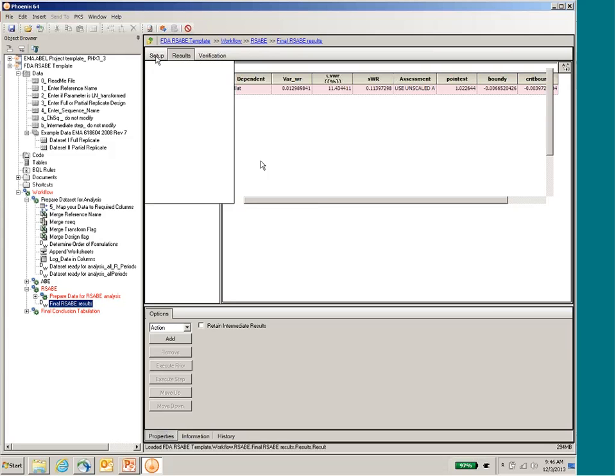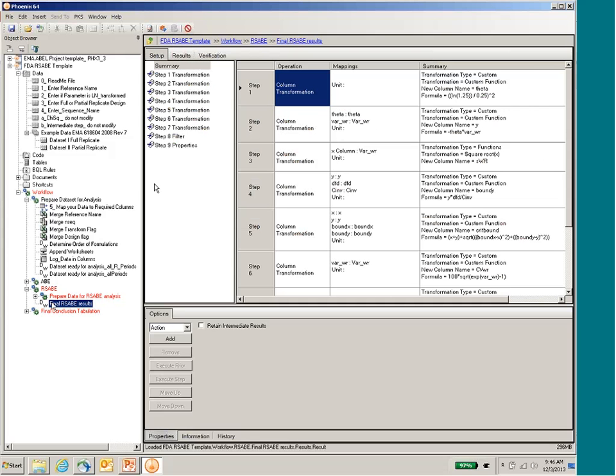How to run these is, you need to highlight the data wizard, go to the setup tab and highlight the last step. But every time you highlight it, it needs to flash. It needs to do this. Okay, so it's doing something even though you have not clicked the execute button. That's actually a good sign. If nothing happens when you highlight it, then you need to go to a previous step and then back to the last step.